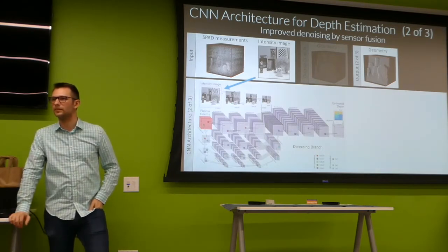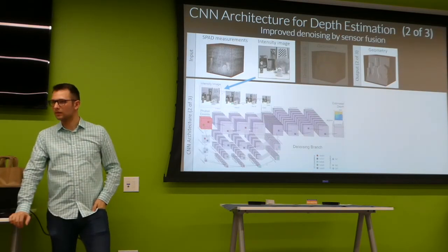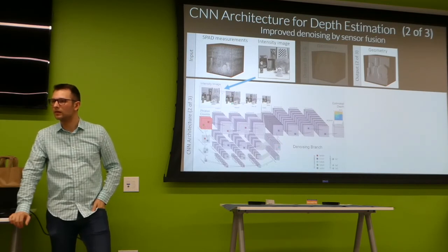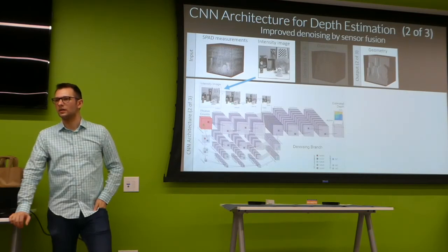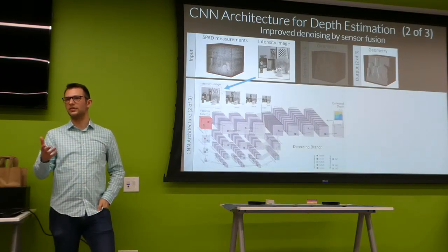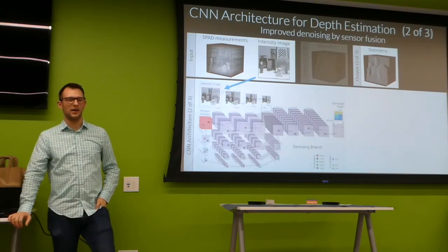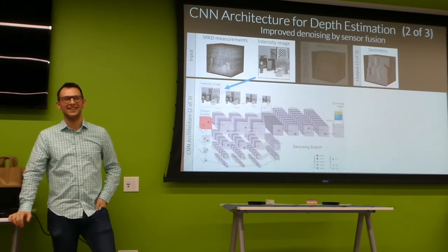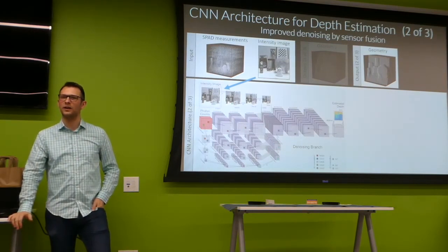You did work with both single-pixel GMAPDs and linear-array GMAPDs, which in my experience have neighboring avalanche issues. I was wondering if you dealt with those, or if you had different quality of reconstructions from the single-pixel versus the linear array. The question is, what was the difference between the single-pixel SPADs and the SPAD arrays? The single-pixel SPAD is actually a lot easier to work with. The line array had worse temporal resolution and a lot more noise.